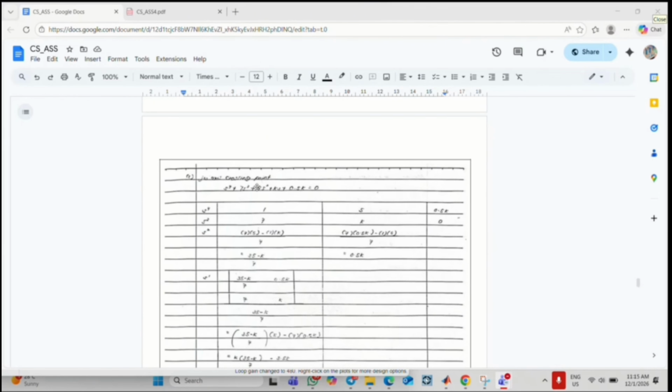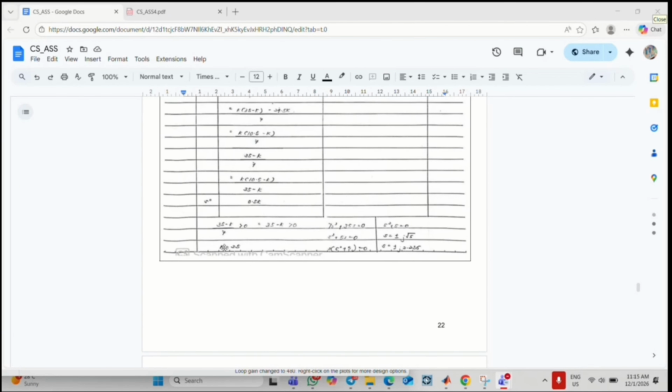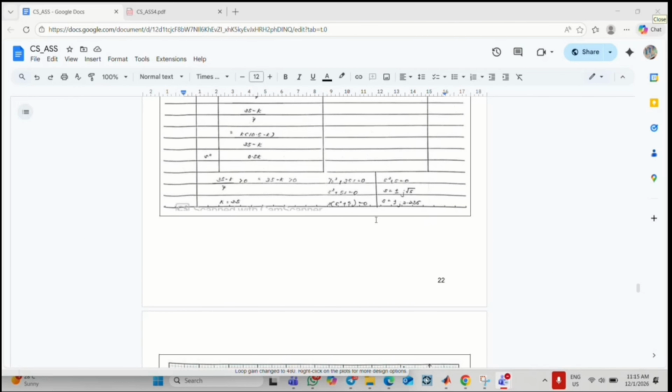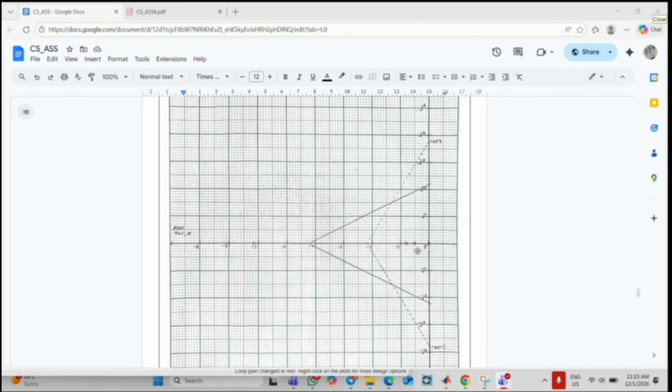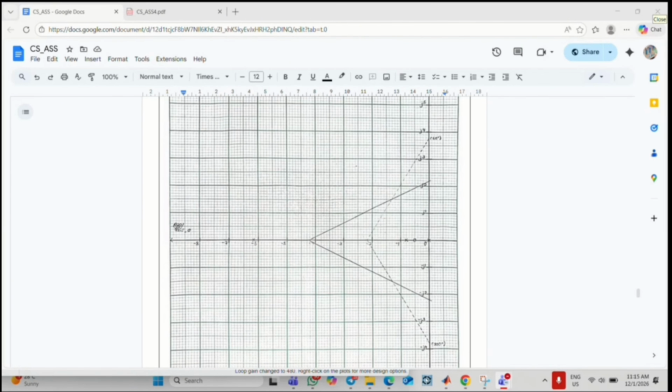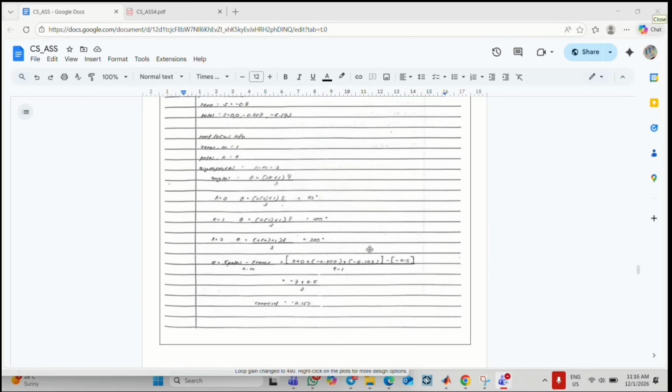Then the jω crossing point is K equal to 35, and the s-plane is plus minus j0.236. For question D, root locus sketch. This is the root locus. The asymptotes are at 60 degrees and 300 degrees, also at 180 degrees. This is the asymptote calculation. The centroid is at negative 2.167.